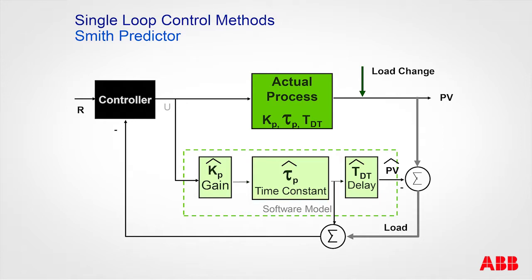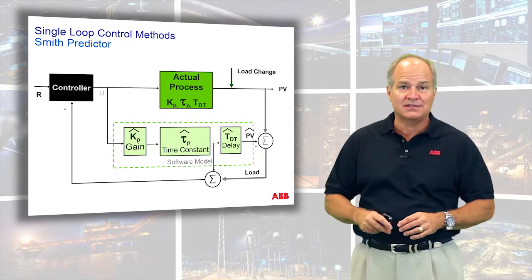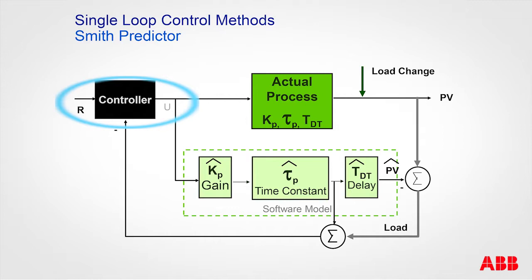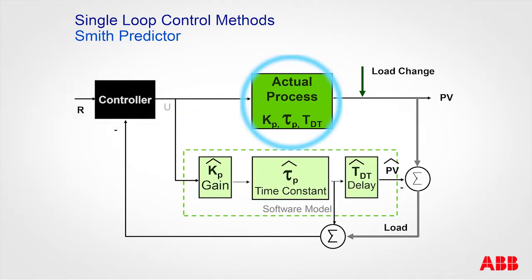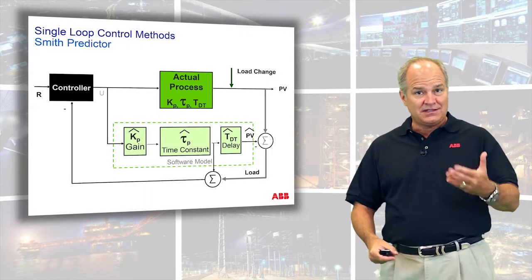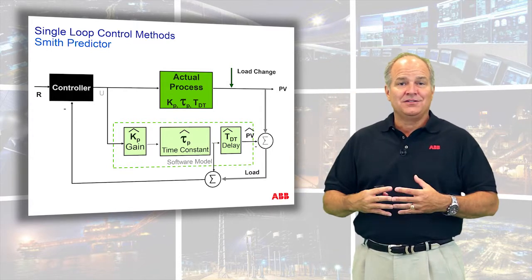That's the picture. So if you look at any of your textbooks, if you do a Google search on Smith predictor, you'll see something that looks like this, where your controller and your actuator are tied to, that's your physical analog output going to your process. Your process does its thing. We measure the process, that's the sensing device, but we also sum it with the estimate of the process. So what we have here is the load. It's this minus this, that's the only difference. And we add that into the process. So literally, we can now change the set point. It works great. And if we have a disturbance, it'll regulate it. That's the secret to the Smith predictor.